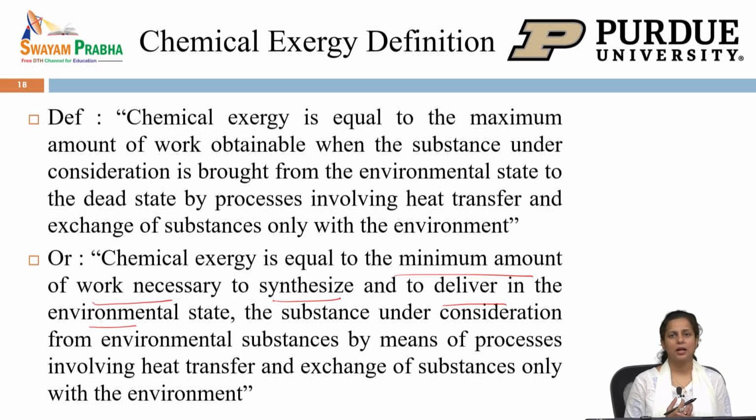When we do this calculation for the species for which we do not have the exergy available, you will see that we take materials from the environment, we make them go through some reaction, and then we calculate the exergy of the material based on the fact that it is now at a different state than it was in the complete thermal and chemical equilibrium with the environment.